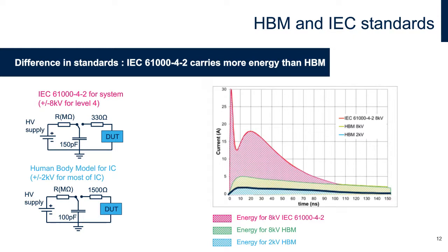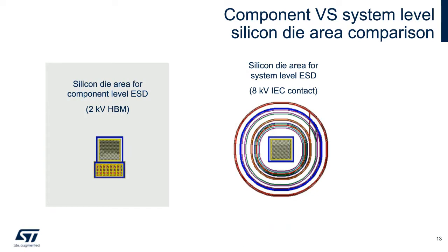While you may wonder why integrated circuits do not feature system-level ESD protection, let's try to figure out what will be the size of the system-level ESD protection integrated in an IC. Here we show two integrated circuit protection layouts using the same scale thanks to pad surface.